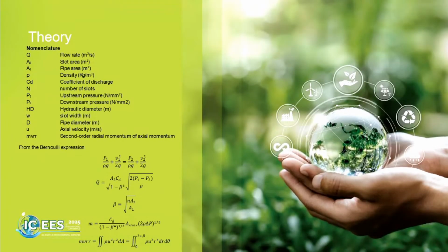The theory governing these, of course, we have the nomenclatures, is the Bernoulli expression, principally the Bernoulli expression. We have the head pressure component at the upstream and the kinetic energy component at the upstream, that equals the head pressure component at the downstream and the kinetic component at the downstream. If the level is the same, the potential components are eliminated.